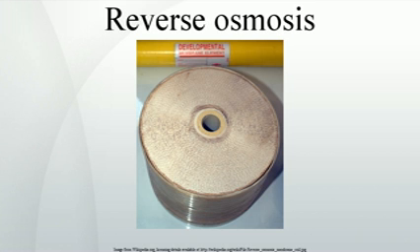Researchers from both University of California at Los Angeles and the University of Florida successfully produced fresh water from seawater in the mid-1950s, but the flux was too low to be commercially viable until the discovery at University of California at Los Angeles by Sidney Loeb and Srinivasa Sourirajan at the National Research Council of Canada, Ottawa, of techniques for making asymmetric membranes characterized by an effectively thin skin layer supported atop a highly porous and much thicker substrate region of the membrane. By the end of 2001, about 15,200 desalination plants were in operation or in the planning stages worldwide.